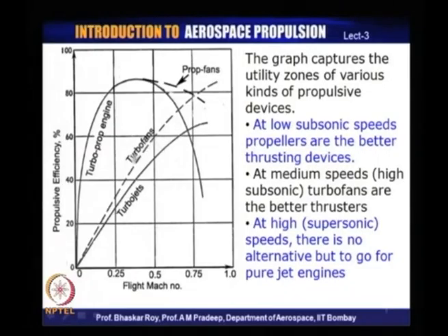And as a result, in a turbofan, as I mentioned in the previous slide, it operates with a high mass flow through the fans and produces a high propulsive thrust, and a small mass flow as a jet and produces a low propulsive thrust, and the combination of the two gives us turbofans which are generally of higher propulsive efficiency.